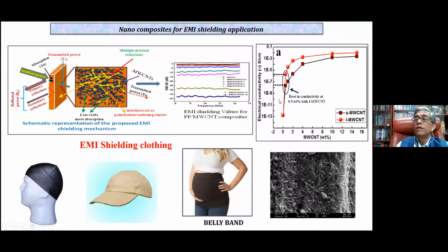And this comes from the conductivity in the nanocomposites, because of the connectivity of these nano-level carbon nanotubes connecting each other at a particular concentration. What is very striking is that even at 4% concentration, you already get the highest conductivity that you want. If we have to get this conductivity with carbon black or even a micro carbon filler, we have to go to maybe about 30% minimum by weight.